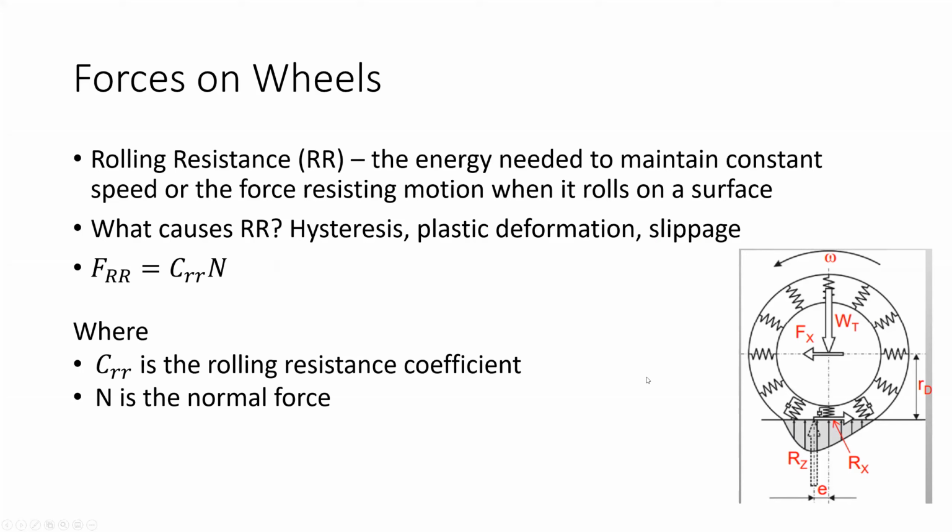So you can actually find this force here by doing statics. If you take the moment about A, you can get the force here on this axle, and then you can take the summation in the y direction to find your other force here.